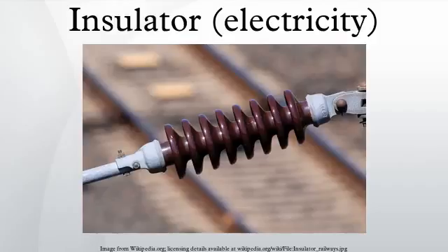Material. Insulators used for high-voltage power transmission are made from glass, porcelain or composite polymer materials. Porcelain insulators are made from clay, quartz or alumina and feldspar, and are covered with a smooth glaze to shed water. Insulators made from porcelain rich in alumina are used where high mechanical strength is a criterion. Porcelain has a dielectric strength of about 4–10 kV per millimeter. Glass has a higher dielectric strength, but it attracts condensation and the thick irregular shapes needed for insulators are difficult to cast without internal strains.